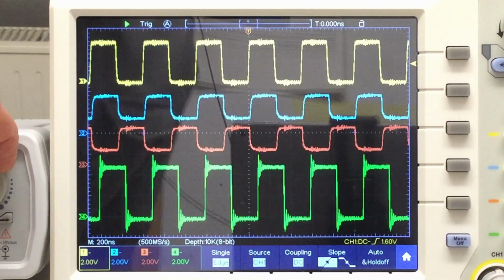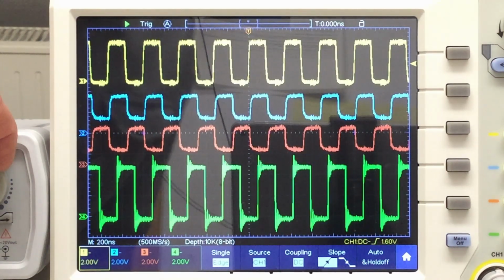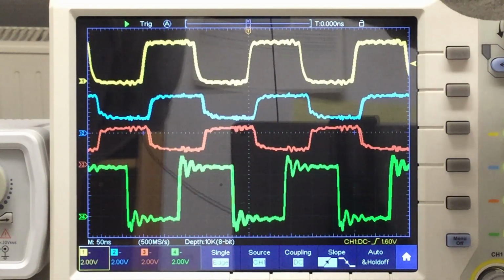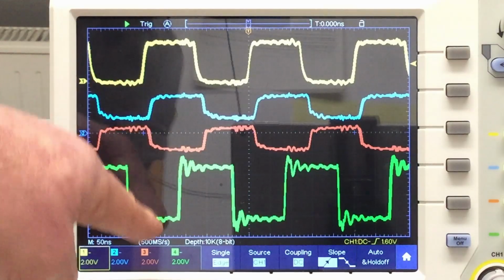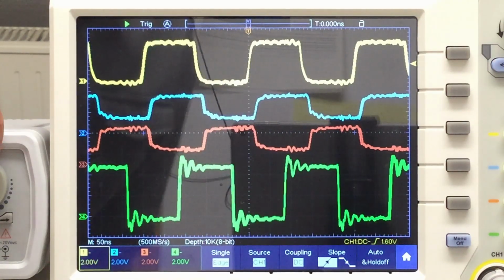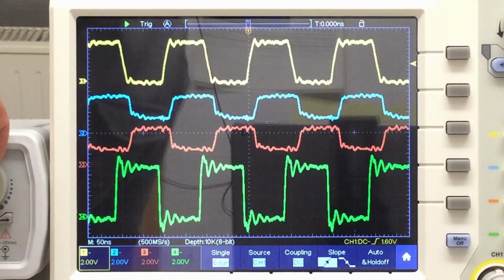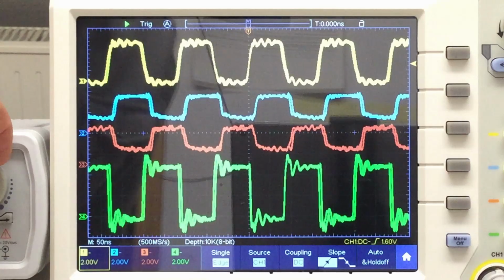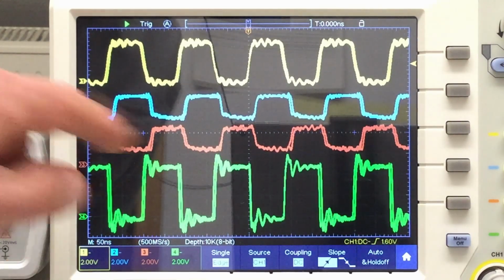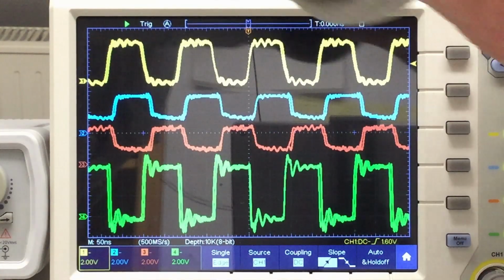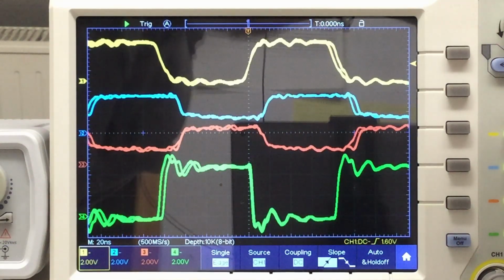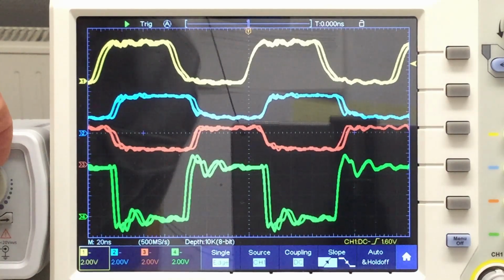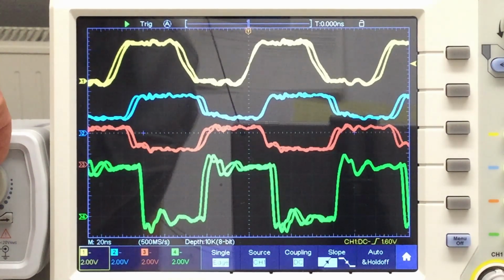to 2 megahertz, looks good, 3 megahertz, looks good, 4 megahertz, let me adjust the time scale a little bit. Ooh, bad ringing here everywhere, but anyway, let's go further, 5 megahertz, yeah. I talked about the ringing, that's really a breadboard artifact. 6 megahertz, now we are experiencing some jitter, but that should be okay. Let me adjust the time scale again. 7 megahertz, yep. 8 megahertz, yep.